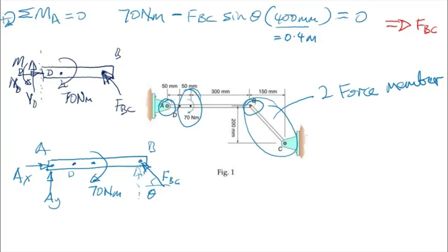From this free body diagram of the section, we can then find the values for ND, VD, and MD: the moment component, the shear component, and the normal load component, which are internal loads to component AB. They are acting internally, so they are called internal loads.